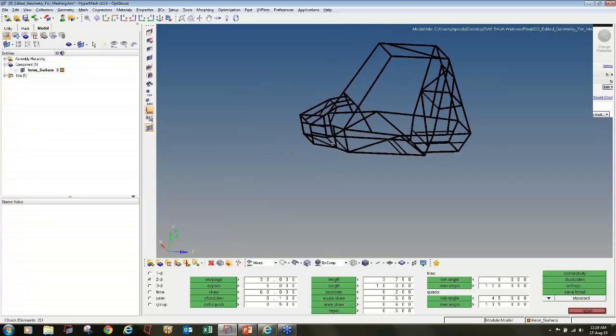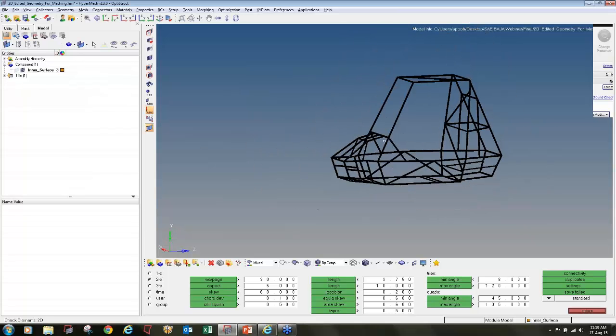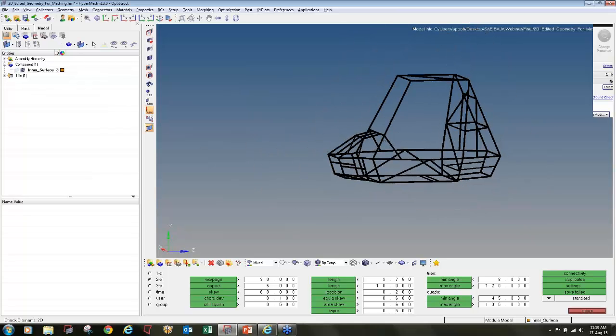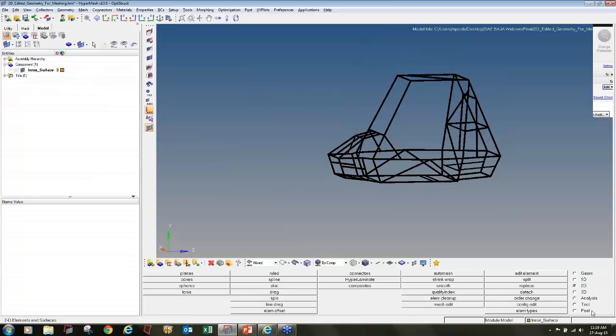Now my meshing and element quality, connections, everything is done. Now I will go further. That is applying the material properties, updating the component, creating loads and boundary conditions, applying load step, that is defining the type of analysis, and solving the file. So this is a step-by-step process.